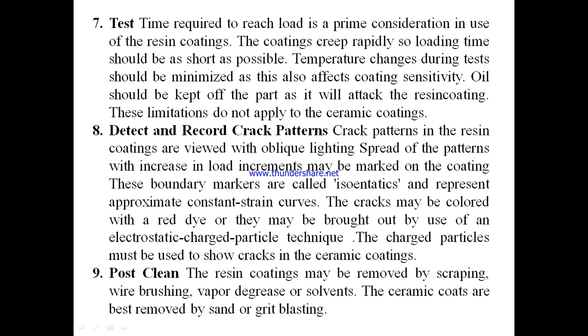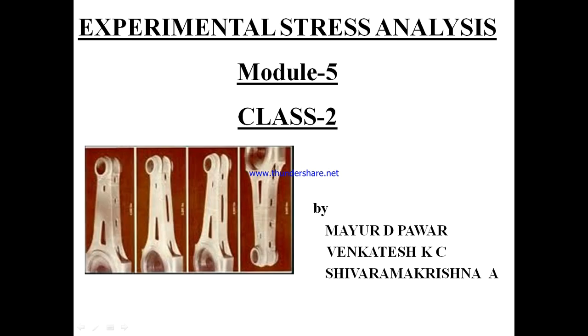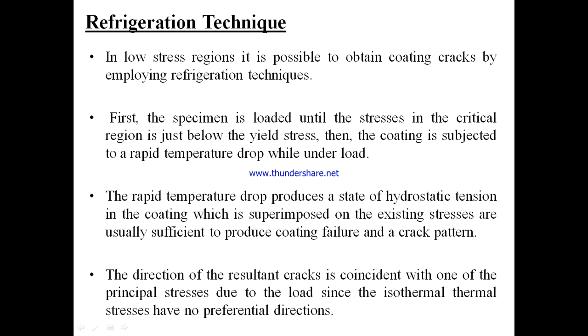We will start with the refrigeration technique. In low stress regions it is possible to obtain coating cracks by employing refrigeration techniques. First the specimen is loaded until the stresses in the critical region are just below the yield stress. The coating is subjected to a rapid temperature drop while under load. The rapid temperature drop produces a state of hydrostatic tension in the coating, which is superimposed on the existing stresses, which are usually sufficient to produce coating failure in the crack pattern.